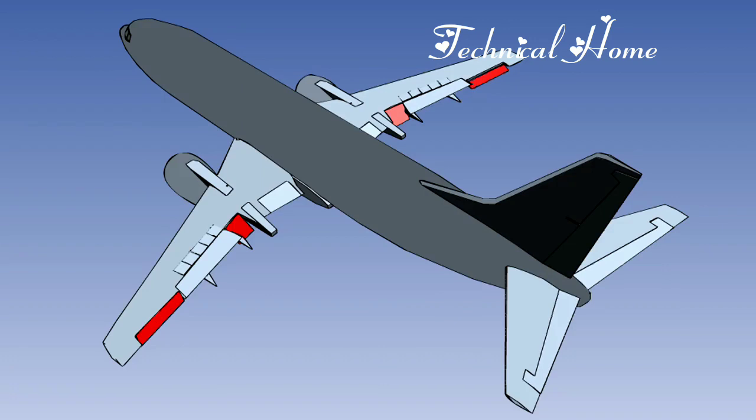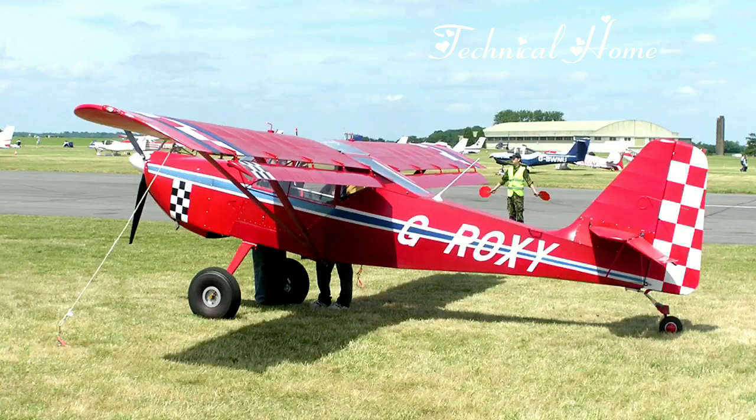They then move differentially from the droop position to give lateral control. This method is used throughout the Airbus fleet. Another system uses the trailing edge movable surfaces to perform the operation of both flaps and ailerons. Such devices are known as flaperons. They are shown here on the SkyStar Kitfox.